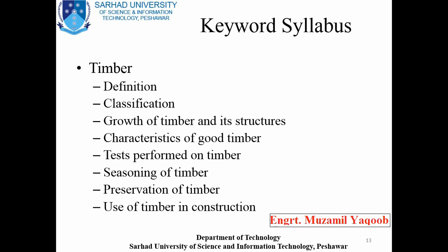Growth of the timber means the study of its cross section, its annual growth in different climates or in different seasons, for example in spring and in summer. Then come its characteristics, which are hardness, strength, meaning sufficient strength to resist heavy structural loads when we use timber in construction. Toughness, which means to resist shock due to vibration, also called vibrating loads. Another one is durability, and the last two are appearance and color.